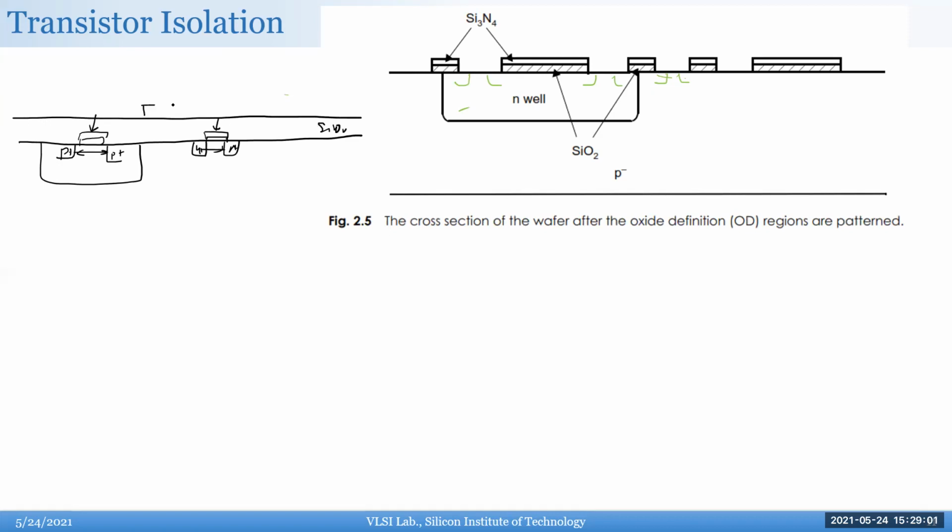So let's say there is a long piece of metal going on here. You apply a voltage. Now this silicon dioxide might turn on a channel here and short it, because this also looks like a MOS between this device and this device here. If there is a channel here, they'll conduct, right? So that's the whole idea of isolation: you want to make sure that you don't accidentally short two devices adjacent to each other by having some other metal layer form a channel.